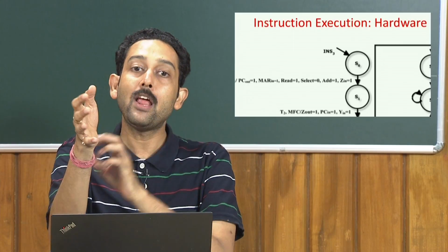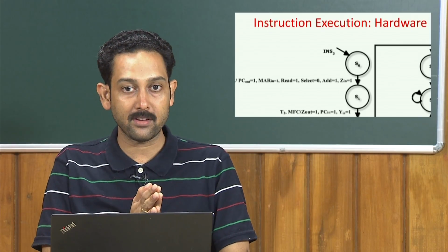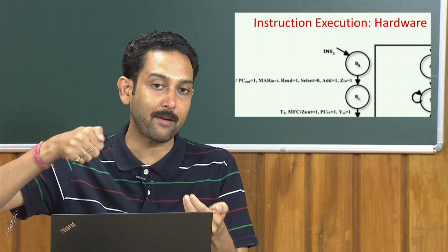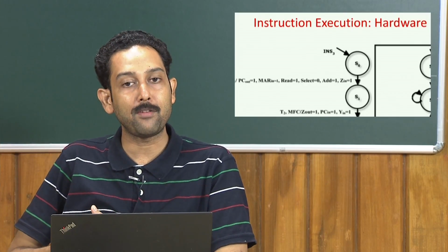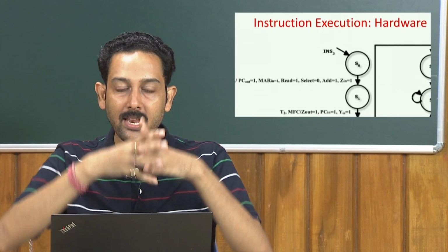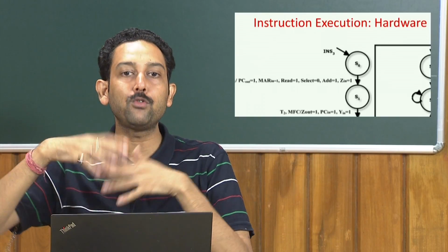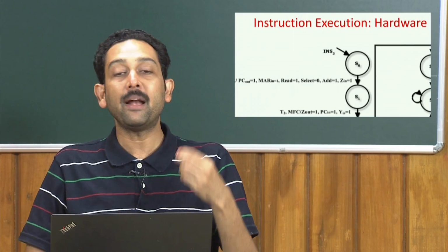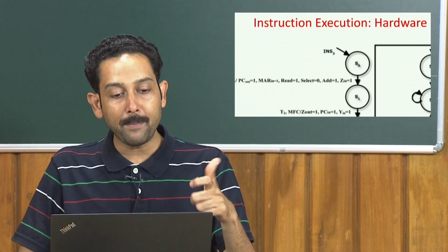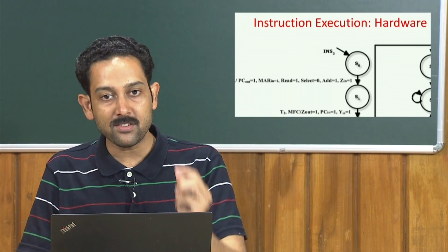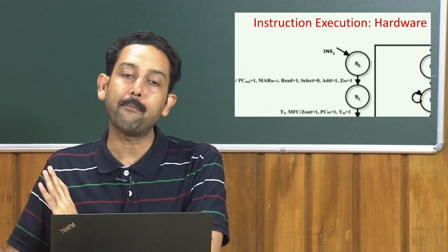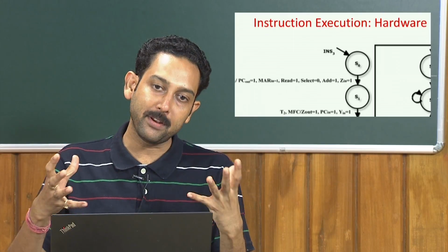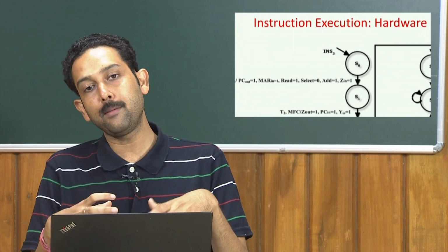So, of course, you will have an optimized hardware implementation, because maybe the first 3 stages are similar for everybody, and the last 2 states are similar for everybody. So, I could have made a merged machine and then keep on branching and joining, which will give me a better optimized machine, but it will be slower, because you will now be depending on the state as well as the type of instructions, and again you will be joining and merging. So, this hardware size will be a bit smaller, but it will basically be a slower design.